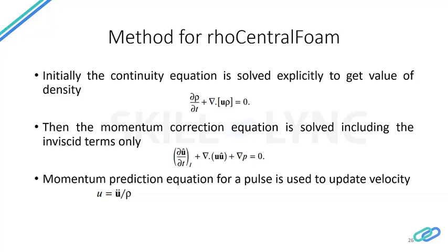As we spoke before in the fvSchemes and fvSolution slide, the d by dt and gradient solvers have their own particular named solvers. These matrix operations are performed on each of these equations based on the particular algorithm that we chose. I say that very loosely.